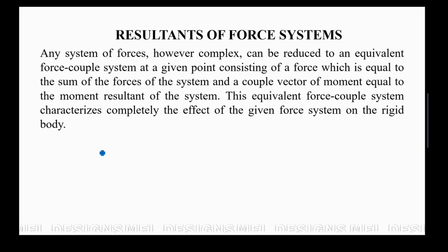So any system of forces, however complex, can be reduced to an equivalent force coupled system at a given point consisting of a force which is equal to the sum of the forces of the system and a coupled vector of moment equal to the moment resultant of the system. This equivalent force coupled system characterizes completely the effect of the given force system on the rigid body.